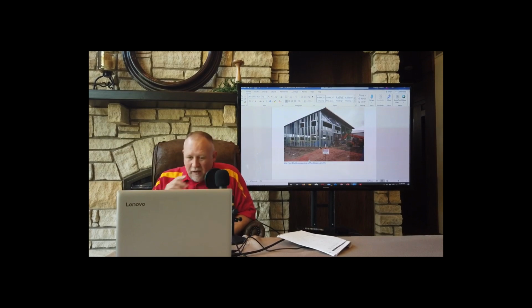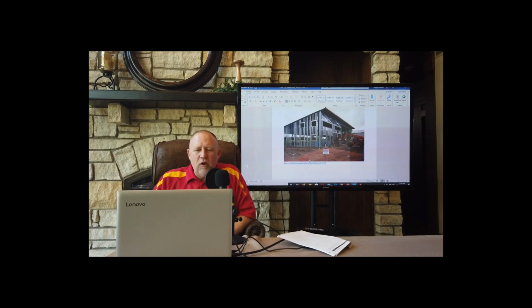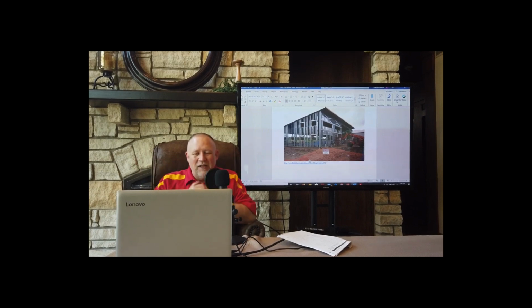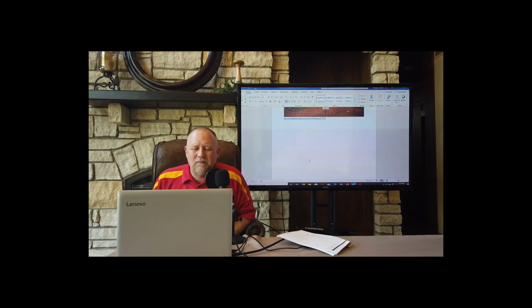And yes, that is a very, very real effect. Basically, what that tells you is, if you're putting insulation between steel studs, you are wasting 60% of that insulation. It's actually a terrible place to put insulation. And I know most contractors will see that void space and they'll think, oh man, it just seems wrong not to put some type of insulation there. Well, you're actually not doing a whole lot of good putting insulation there. So just remember that for future use.